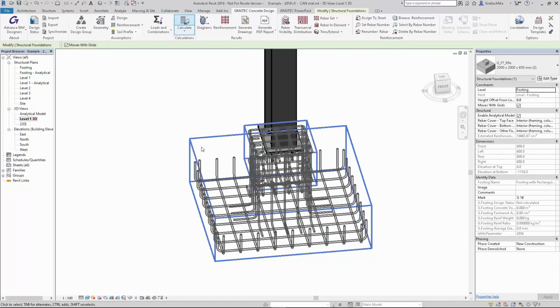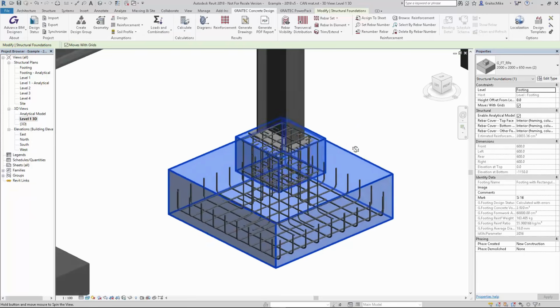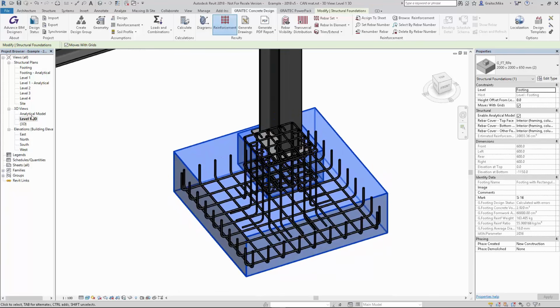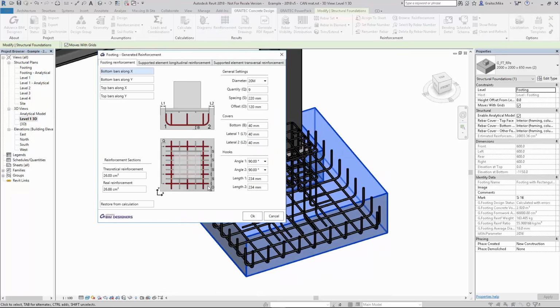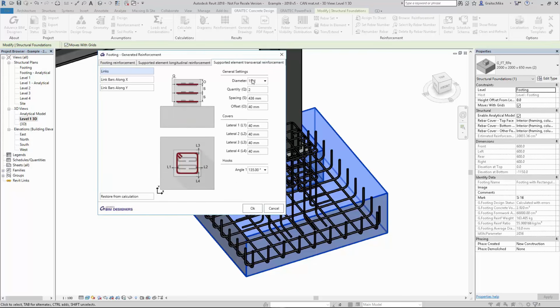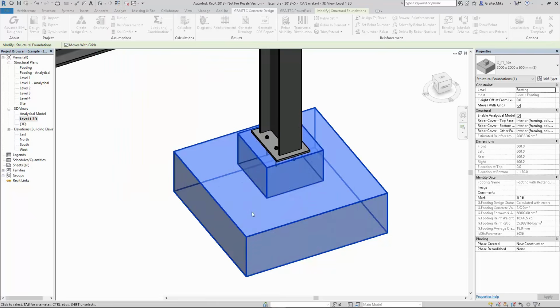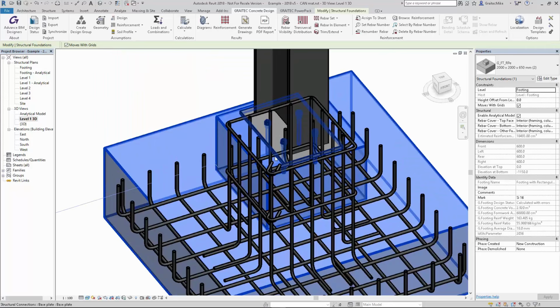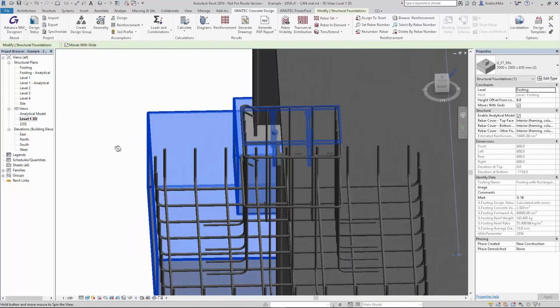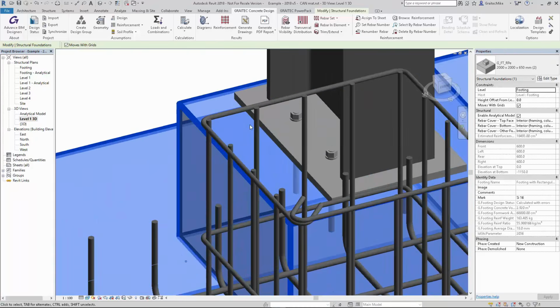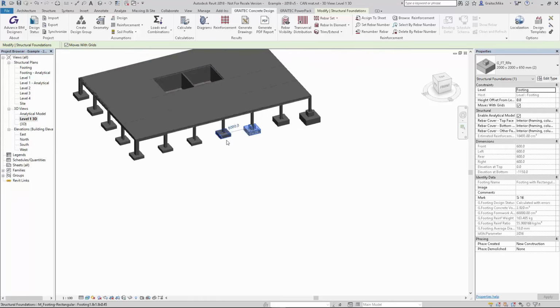Some of you may know the process it takes to recreate a family element. You need to duplicate it and make sure you punch in the right dimensions. So in using the BIM designers, we could easily also modify the rebar. It's not a one-time generation. We could also consult dialog boxes with graphics to make sure that the rebar that we placed is what we want. And then we could do whatever modifications we want to this rebar. So we could easily consult dialog boxes to make sure it's what we'd like.